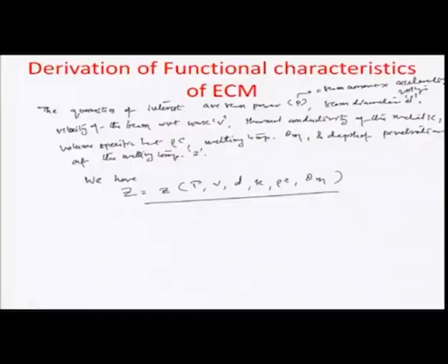So, let us start with power. Power, for example, is force into distance per unit time. So, the basic dimensions would be that of force, that is M L T minus 2, times L divided by T. So, this is M L squared T minus 3. Similarly, you have for velocity L T minus 1, d of course is the diameter, so it has the dimensions of length. k here is the thermal conductivity; let us just write this down here, do not have space.